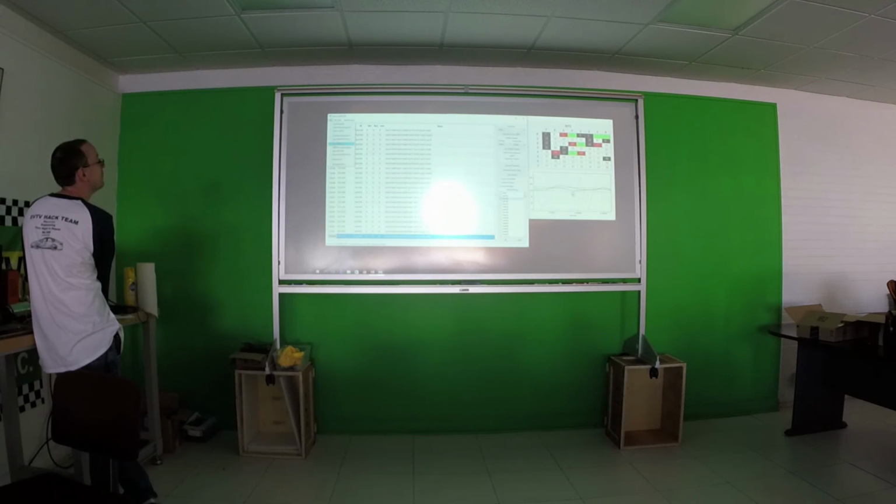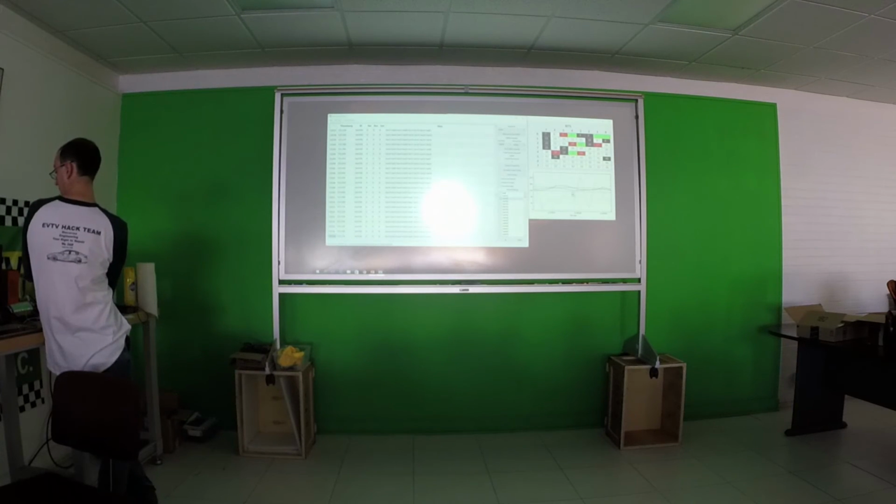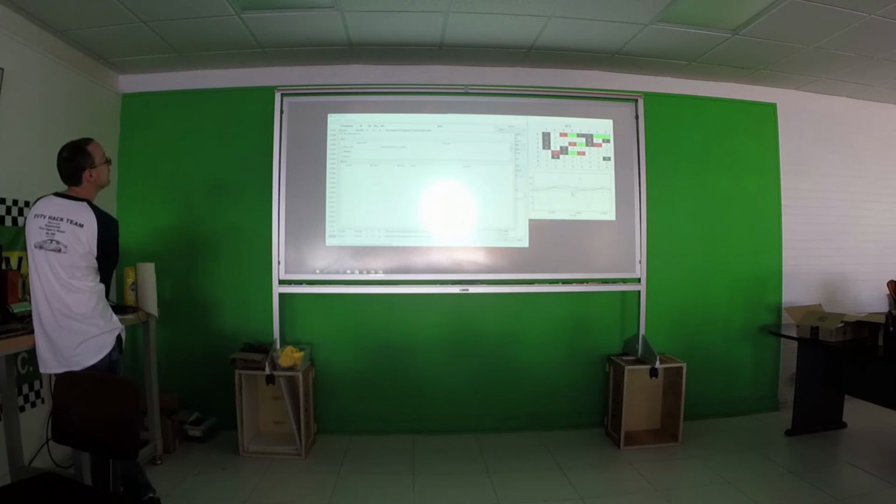I'm going to take a quick step back to show the DBC files, because before we get to graphing, it's really handy to have the DBC file loaded. I'm going to load up Tesla version 8 here. Go quickly through the DBC editor. This is where you would set up the nodes. I have inverter here as one of the nodes. The inverter sends these messages, which I've just labeled inverter message 1, 2, 3, 4, 5, 6. But these are the IDs that the inverter sends. So I know that the inverter will send messages with ID 106.